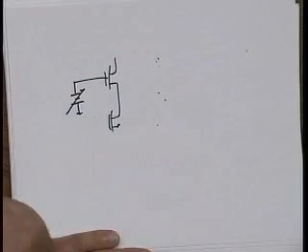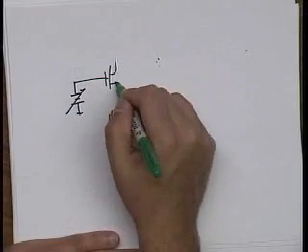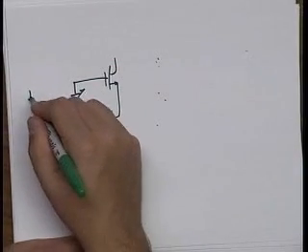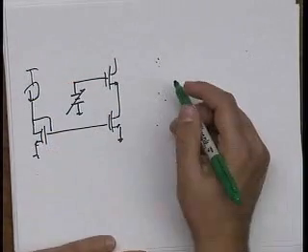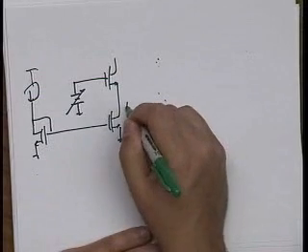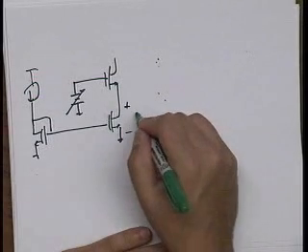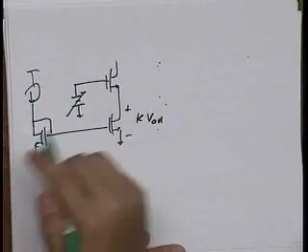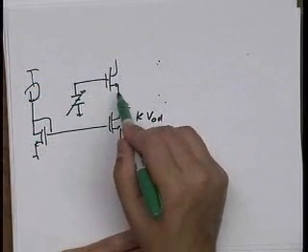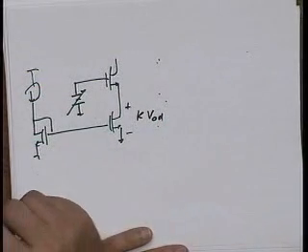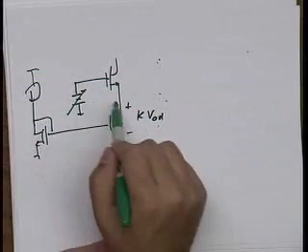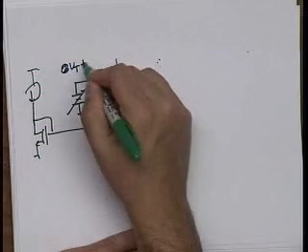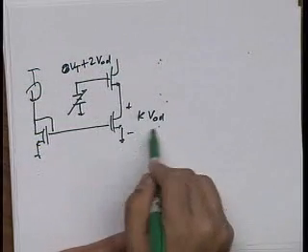If I could magically program a voltage into here, what I'd like to do is program a voltage which is some fraction or some multiple of the V star of this device. I'll just call this V overdrive because it's more intuitive. For a long channel device, I know I would program this voltage to be exactly overdrive, right? So this voltage here would be 1 VT plus 2 overdrive, to keep this voltage here at overdrive.